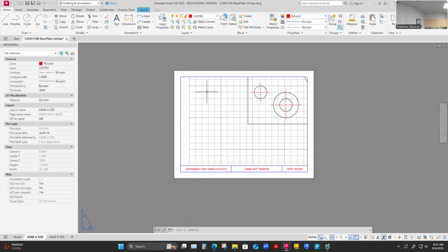It's more often that you're putting multiple things on here and you have these individual viewports, and your viewport's only showing the minimum data on that part that it needs to show, because then you're leaving space for something else to be put in here through another viewport. We haven't done that yet and we don't do that for a little while. So don't misunderstand that your viewport should always be expanded to the full area of drawing that's available.